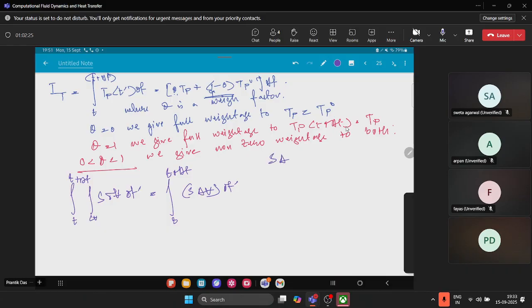If it is constant, then A is equal to SP, otherwise A is equal to AC plus SP Tp. So SP Tp takes into account the linear variation of the source term with the temperature profile. The first one is a constant term, and the second one is a linear variation of the source term with temperature.